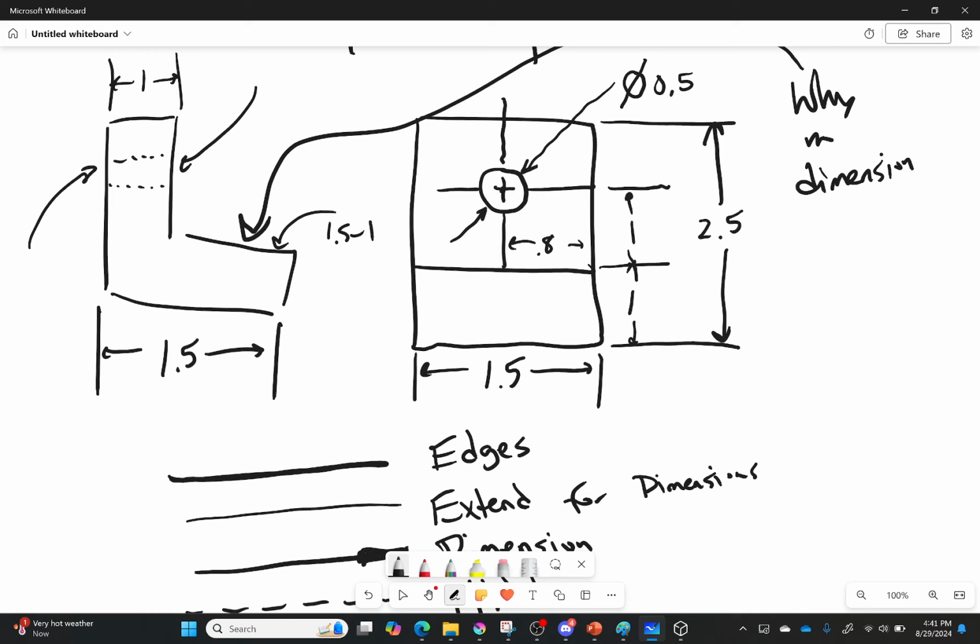And as a note, when you do dimensions, you can have them going to a solid line. You can just imagine that there is an extension line that is hidden by that solid line. So that center line is what I use to help add my dimensions that tell me where the position of that circle is. And I'll do that for any circular object, anything that has a circular cross section. As a note, I also add a center line in my side views. I just put it right along the middle of my shape if it is a circular cross section. That just tells me where it is.